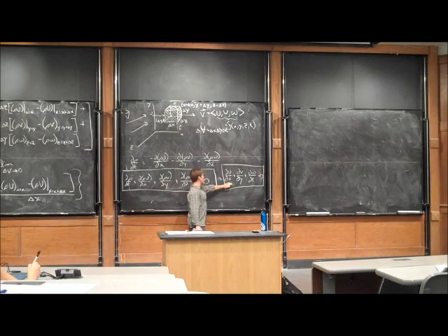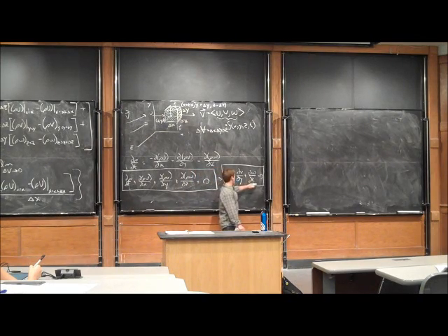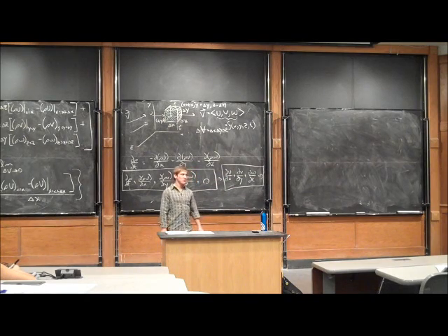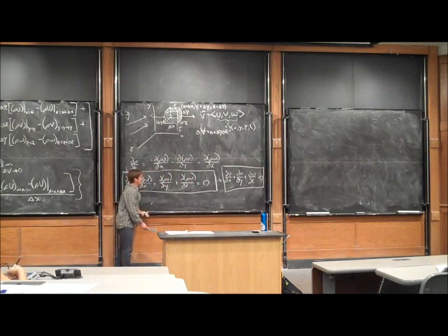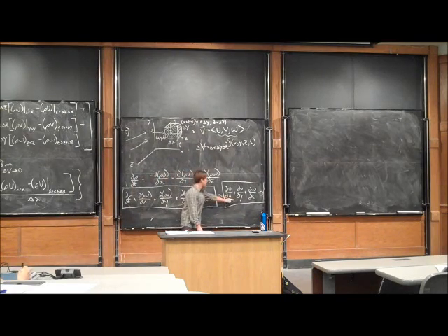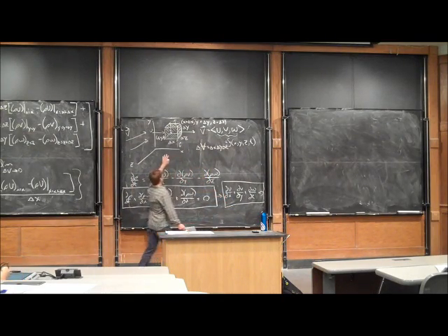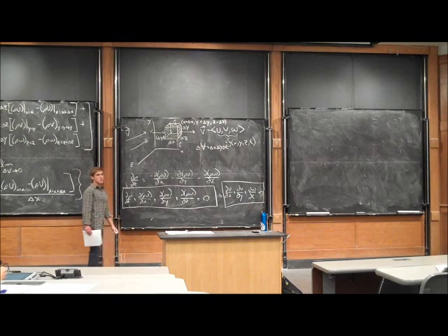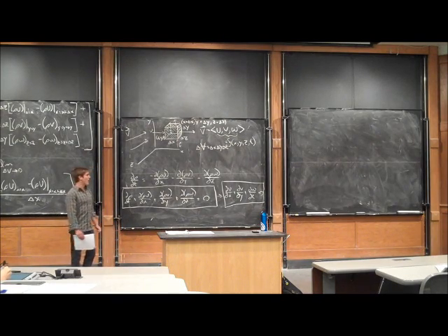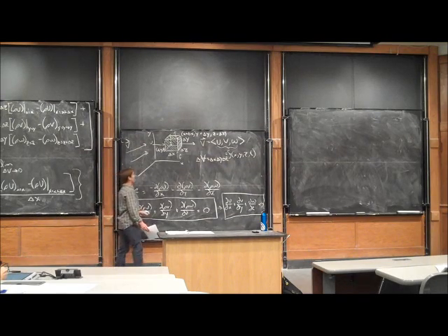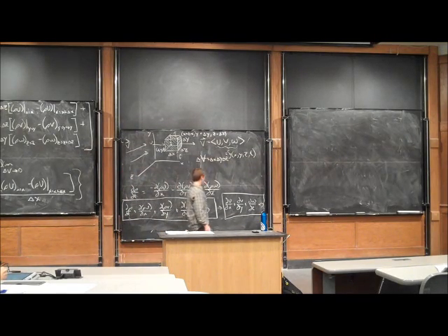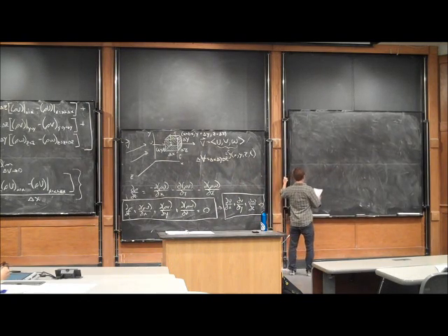This term that you see right here, ∂u/∂x plus ∂v/∂y plus ∂w/∂z, is often called the dilation of your velocity field. What that pretty much says is that if this is not equal to 0, our control volume is going to be growing or shrinking, because the mass flow coming into the control volume is not going to be the same as the mass flow leaving. So that's why it's often referred to as a dilation of your velocity field.